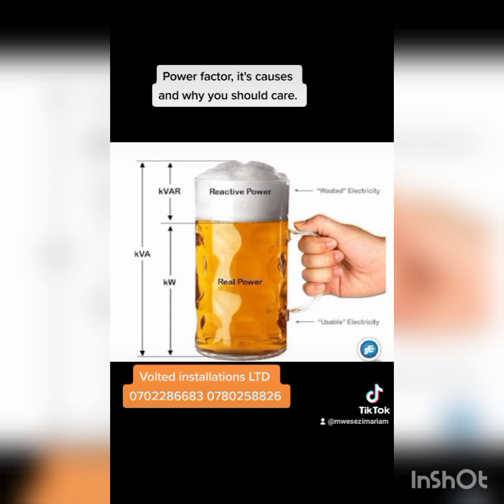So why should you care about having a low power factor? The first thing is it lowers the utility costs. It reduces the real power demand billing, the KVA. Like I said in the previous video, KVAs are billed. And the second thing is you eliminate the penalty. Having a power factor less than 0.85, you incur a penalty with the utility companies.